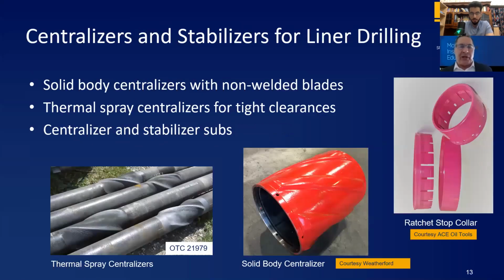Talk about centralizers and stabilization. We recommend solid body centralizers with non-welded blades. Here's an example of a solid body centralizer courtesy of Weatherford. Basically, this is one piece of steel. The blades are part of the body right here, so there are no welds.